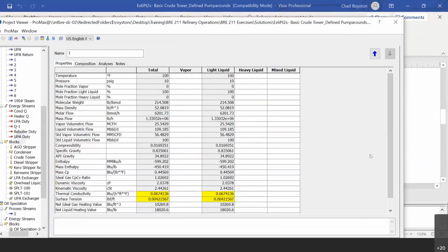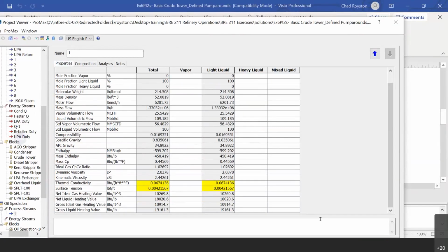Hopefully that's a nice little tool for you to experiment with. Like I said, it's nice that it's customizable. You can shift the peak of your sulfur to match what you have. You can override our correlations with specific lab data. So it is very powerful in that you can customize it how you'd like to use it. Yes, this is an approximation based on certain correlations, but it's a good starting point, and we've found it to be very, very useful for defining those sulfur species.